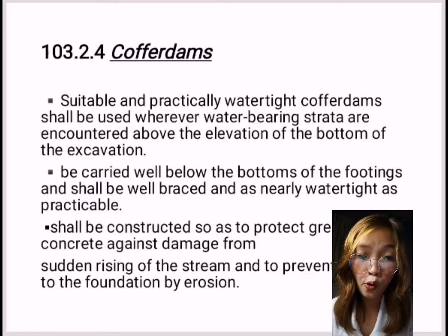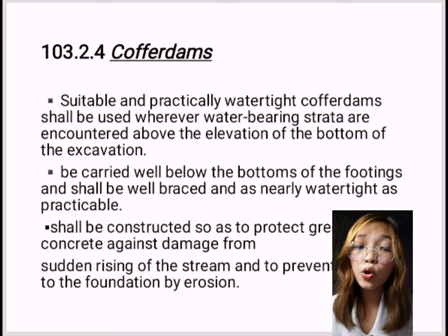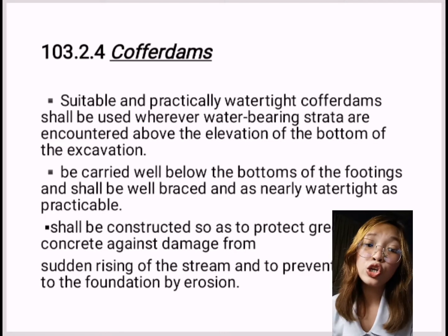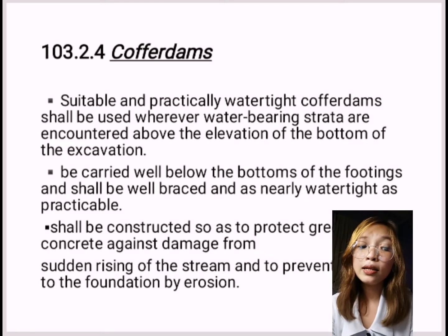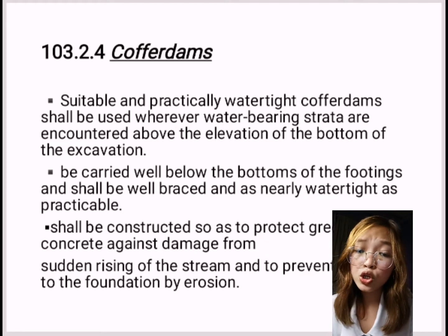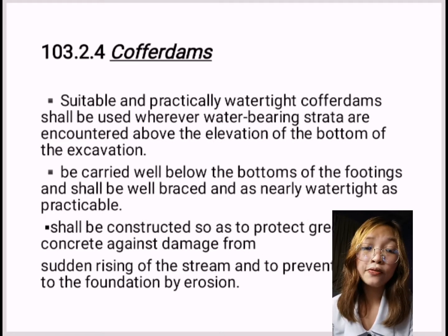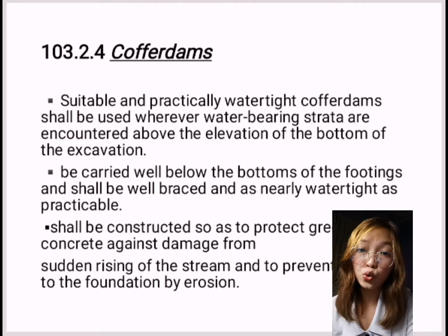outside of the forms. So cofferdams or cribs which are tilted or moved laterally during the process of sinking shall be righted or enlarged so as to provide the necessary clearance. So cofferdams shall be constructed so as to protect green concrete against damage from sudden rising of the stream and to prevent damage to the foundation by erosion.